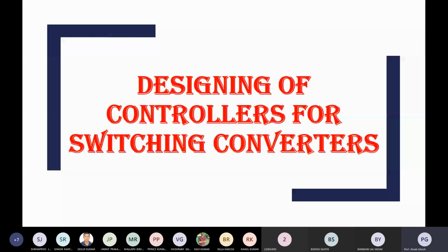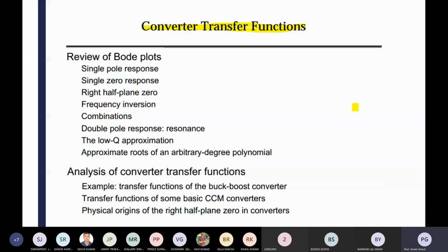Time domain analysis means you have to model the system in the form of a transfer function. If you get it, you can go for the step response. For time domain analysis, normally we do it for the step response and find out the rise time, peak time, the percentage of peak overshoot, and the steady state error and settling time. That is for the time domain response.